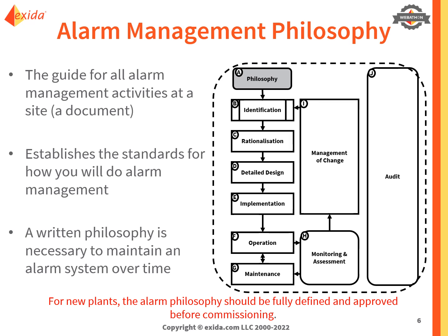It should contain the rules for classifying and prioritizing alarms, for using color to indicate an alarm in the HMI, and for managing changes to the configuration. It should also establish key performance benchmarks, such as the acceptable alarm load for the operator. That's the average number of alarms per hour. For new plants, the alarm philosophy should be fully defined and approved before commissioning. So this document is the starting point and will lead on to creating the master alarm database.